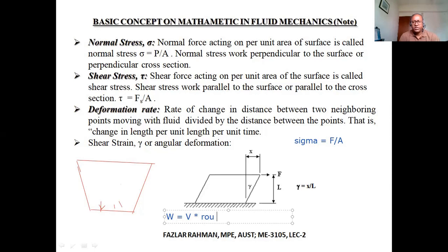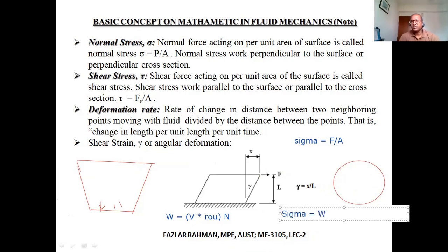This weight of the fluid has the unit Newton. And where is it working? Just on the small area of the bottom. What type of area is at the bottom? It is circular, right? If you have the diameter of the bucket, you can figure out the area. So your stress sigma will be force by area. What is the force now? That means W, the weight of the water. You divide by area, you get the stress. Just remember, stress always works perpendicular to the surface or perpendicular to the cross section.